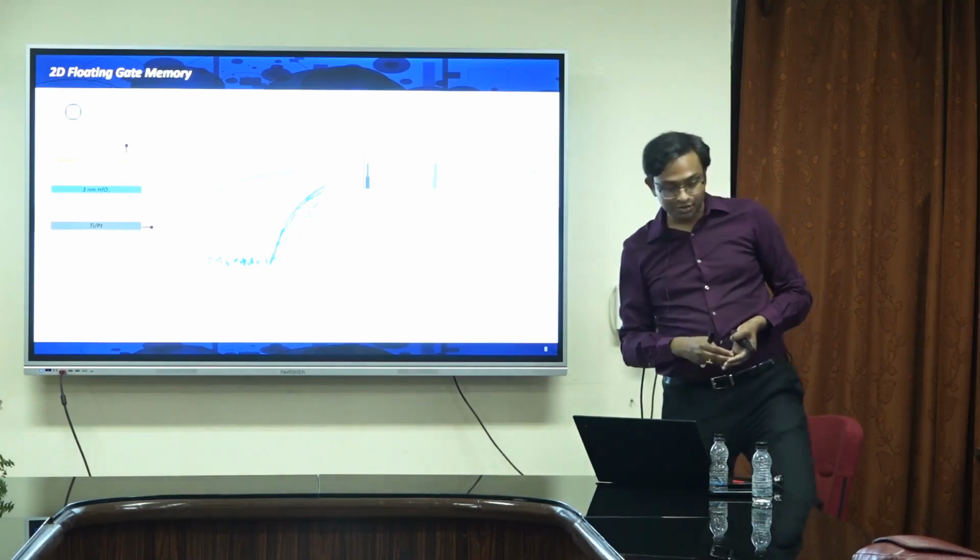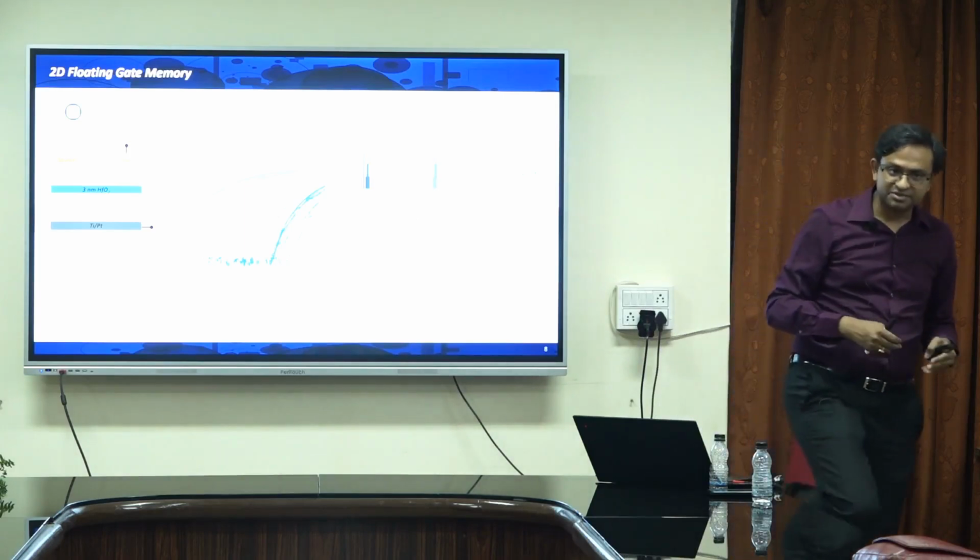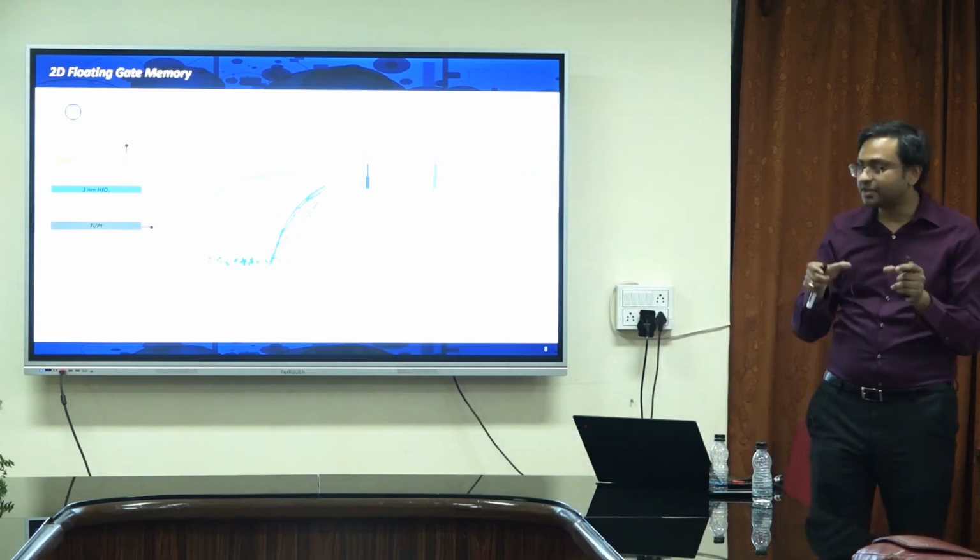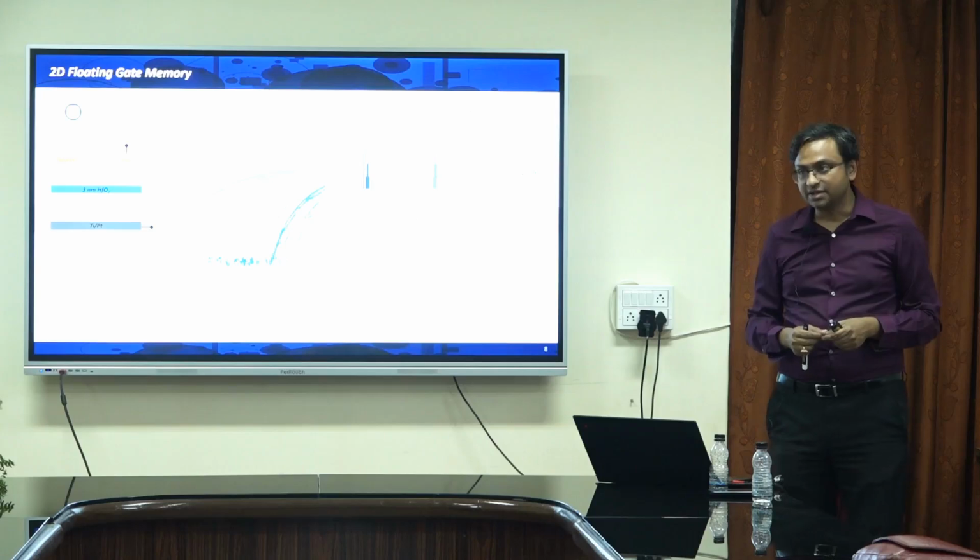The source drain material we are using is actually Ti gold, sometimes nickel gold, based on what makes a good contact to the 2D material.